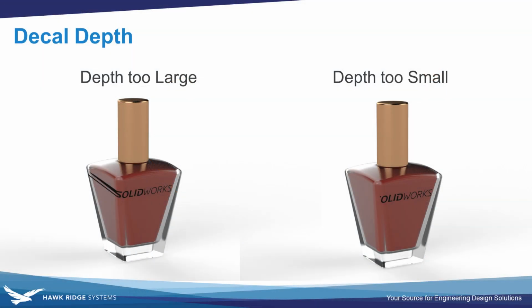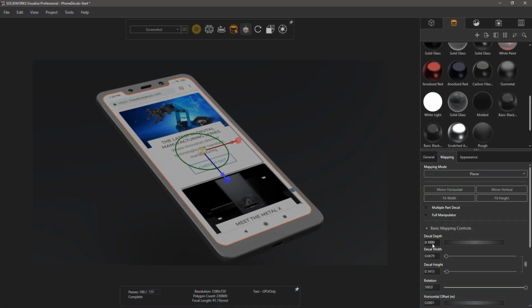There's another parameter to pay attention to, which is decal depth. As you can see on the screen here, if you're applying and projecting the decal onto curvature, that decal depth will control how far it wraps around the model. So you just want to choose a nice value that represents the behavior you want. Anytime we're projecting onto a flat surface like we are here, we don't have to worry about the decal depth.